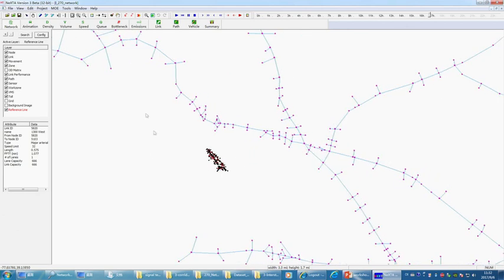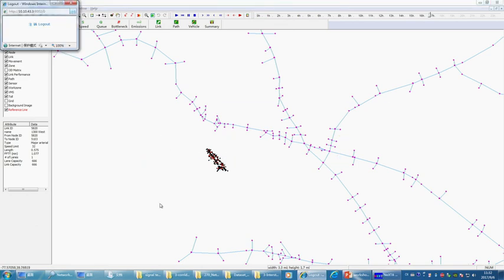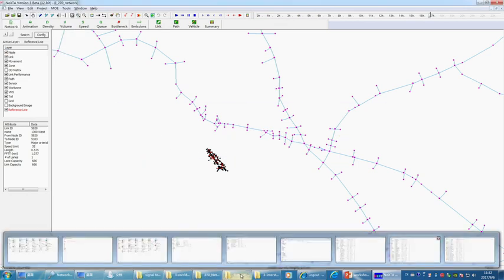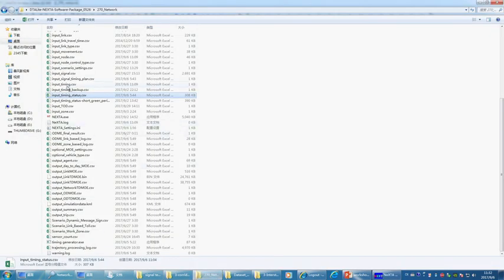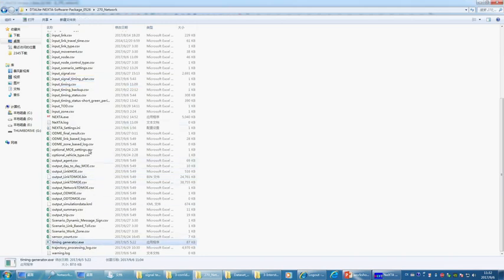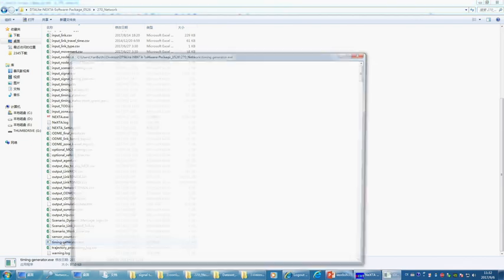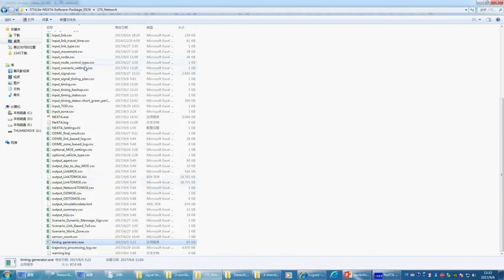Okay. So after you have these, we should be able to go back to the signal representation. You should be able to maintain a combined input timing.csv. So this is input timing.csv, and the corresponding input signal timing plan becomes the central pieces for this signal data hub. With these two files, with the help of timing generator.exe, you can run this exe. You can just have a very quick run here, and it will generate the input timing status as a result.